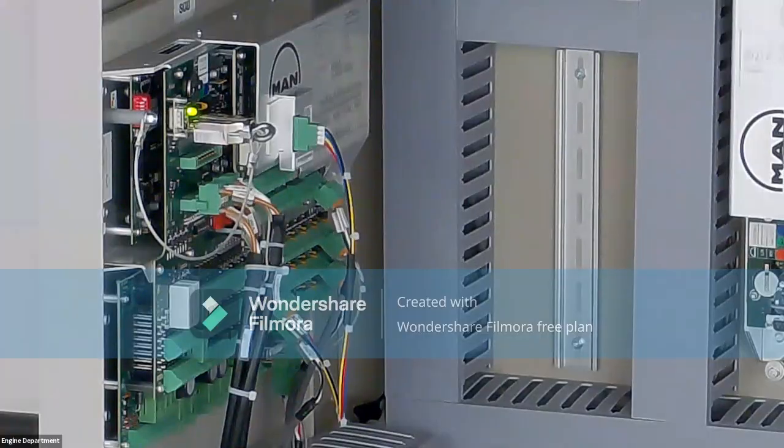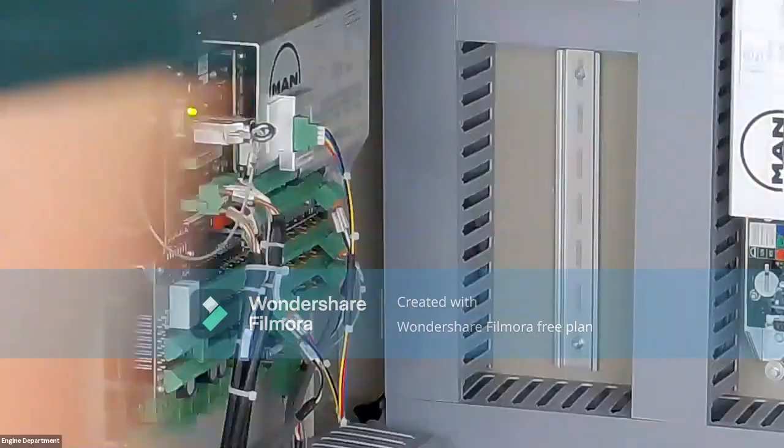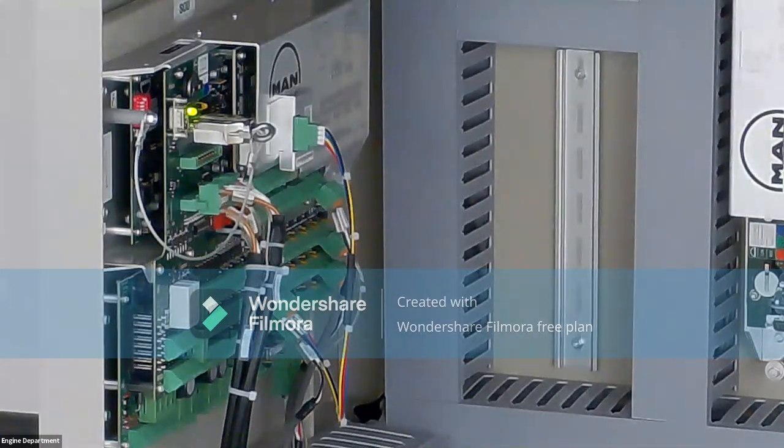They open the cabinet and use external fans to cool down this MPC. All the external electrical equipment surrounding the MPC creates electrical noise, and the electrical noise gives false alarms to the engine. So please always keep the cabinets of the MPC closed in such a way as to avoid electrical noise from the external engine room machineries. So basically they should always be shielded.